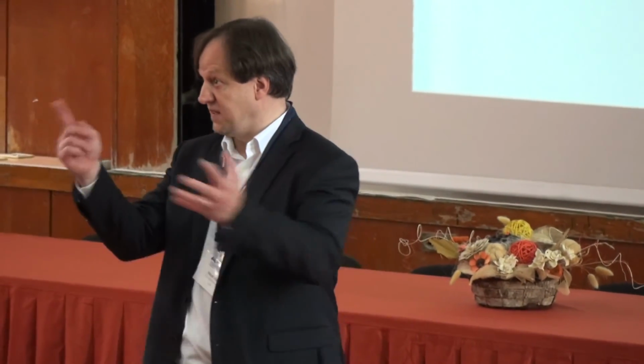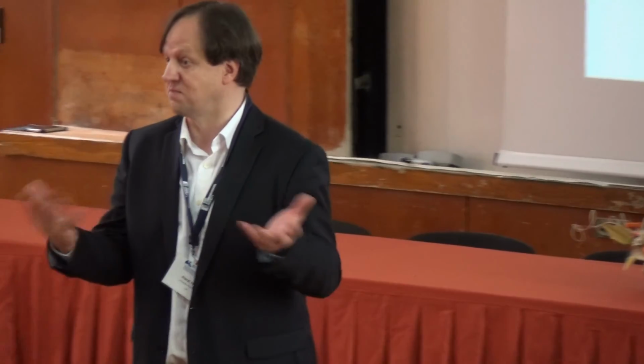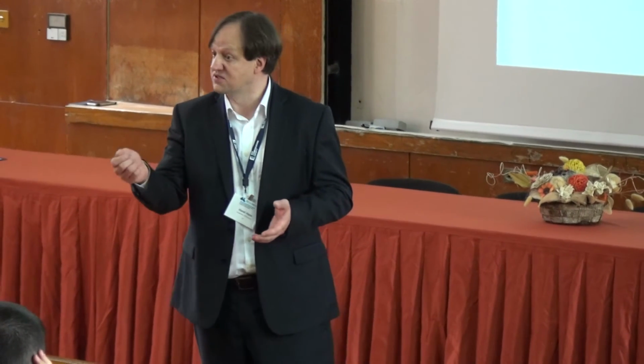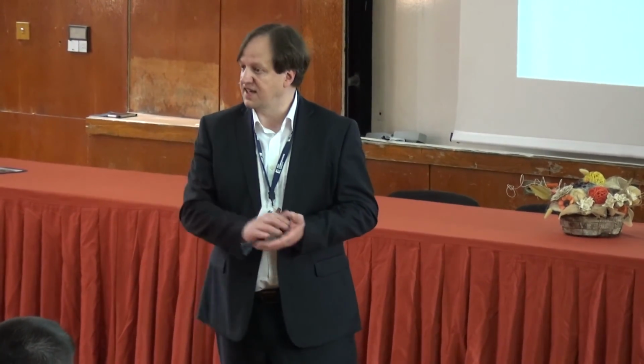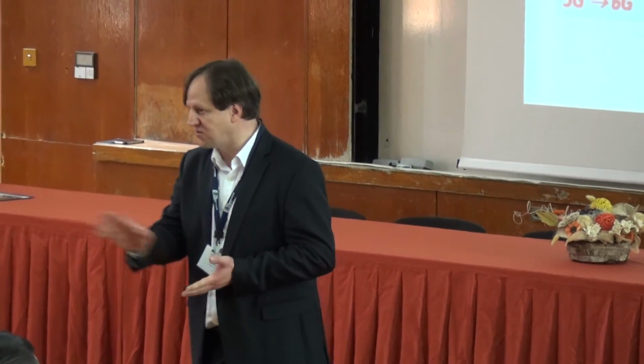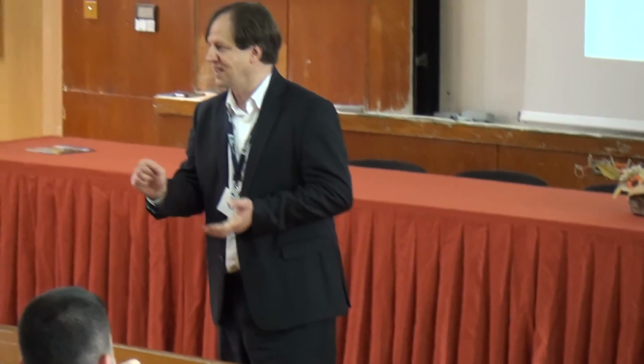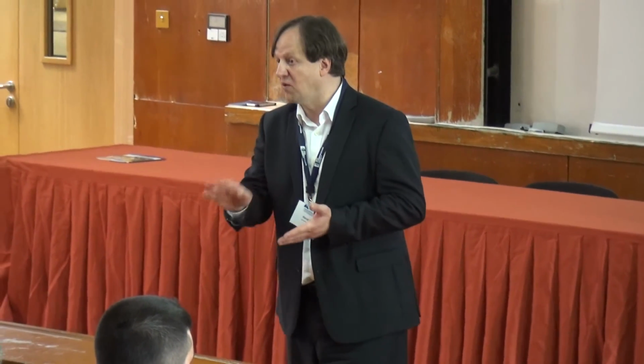You touched upon a very important aspect, which is getting data to the light. But the good thing is that all the lights that we have here are already connected to some network. It's a power line network, and there's a technology called power line communication, which is a very nice home for an application, also standardized. The other is, if you look into a modern lighting installation, you don't find a power connection to modern lights. They have an Ethernet connection and use power over Ethernet. With power over Ethernet, you can supply 60 watts to the device.